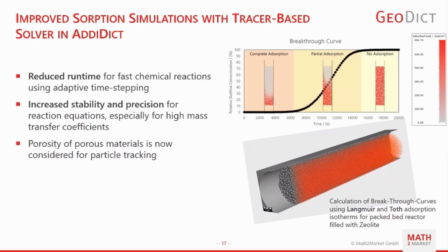And the simulation first computes a velocity field using the standard flow solver, and then particles are tracked through the velocity fields. The adsorption process is simulated using isotherms like Langmuir or Toth, which predict how particles are adsorbed into the adsorbent at the interface.